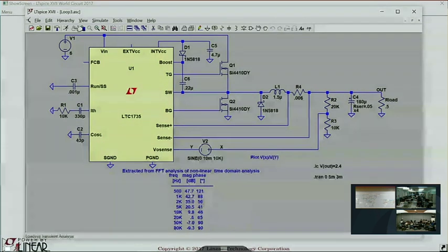That's why it's better, because this circuit regulates current through the inductor. That's what it's doing, so the inductor doesn't cause a phase shift. That's why current mode is better than voltage mode. Okay. Was that fun? A little bit? Good. Now let's continue through the feedback loop.